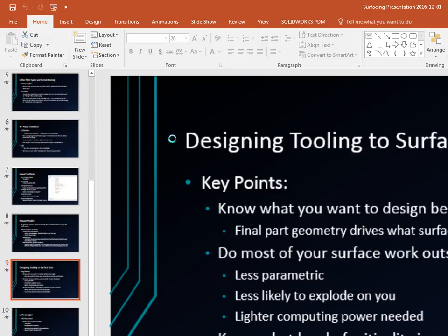Right, and that's what we would typically do too. Especially if this face was flat, and it may even be, I didn't check it, at least perpendicular to the hole. Nope, it's not flat. But if it were flat, we could just use this to get our start plane. Just take a plane off from that by 2 inches and make that our start plane.